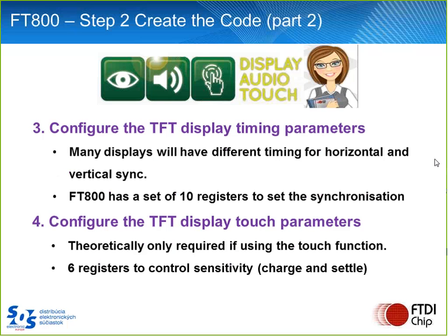Step 4 would be to configure the TFT display for touch. It's only used if you require touch. We have had many applications from customers where they say, we don't need touch, that's fine. However, if you're going to use it, there are 6 registers to control the sensitivity.